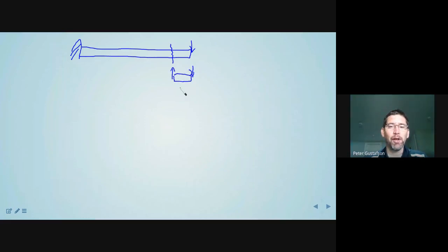Because these have to still be in equilibrium, we can do the sum of the forces in the x, the sum of the forces in the y, and the sum of the moments. It means that at this location, the shear stress magnitude has to be the same as at this location. Left and right-hand side have to be equal and opposite, and the same in magnitude. So I made that arbitrary cut here. I could have made that arbitrary cut here, and I can make that argument all the way up to this point here. Just a fraction of a hair away from that rigid wall, if I took that cut, now that's the boundary, I would find that the integral on that surface still has to be equal to P in order for there to be global equilibrium, sum of the forces in y equal to 0.